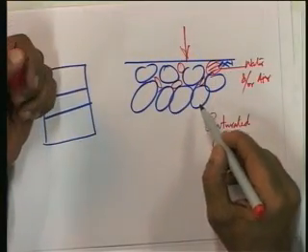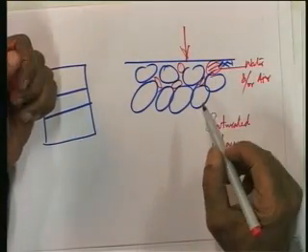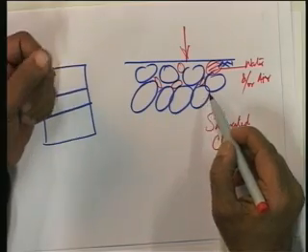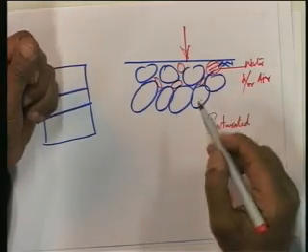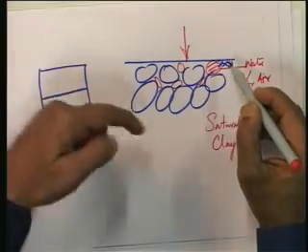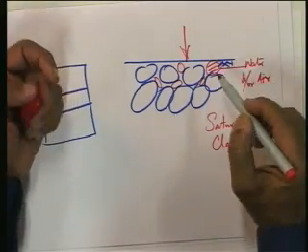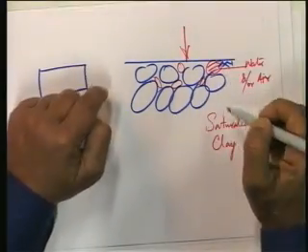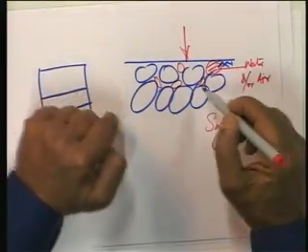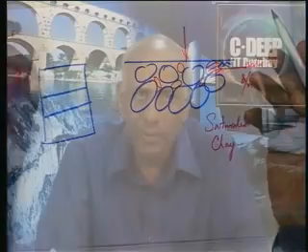We have said already that the solids are incompressible, or the minor elastic deformations that the solids undergo are negligible or instantaneous. So, the next phase is the water, and if the soil is saturated, then all the voids are filled with water, and water is incompressible. And if water is incompressible, if the solids are also incompressible, then how is the compression going to take place?